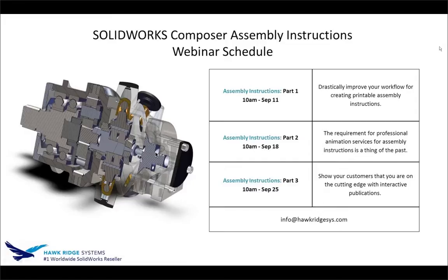And the way that workflow goes is you update your CAD models, you go into Composer, you tell it to update, everything updates. There's a single button press that takes all your steps and saves that out as a bunch of images. It will actually overwrite any images you had saved in the past. Now, since PowerPoint is linked to that, or your website is linked to that, or Word is linked to that, then it automatically updates as well.